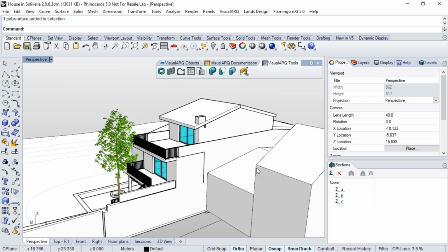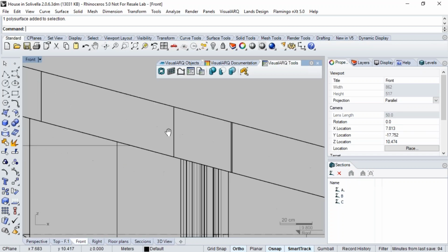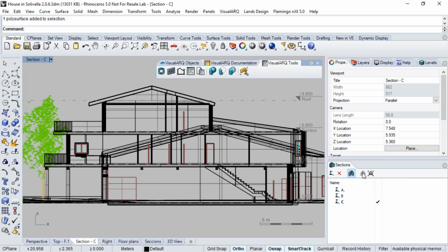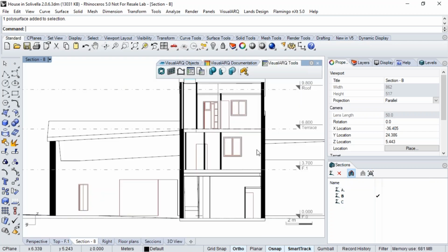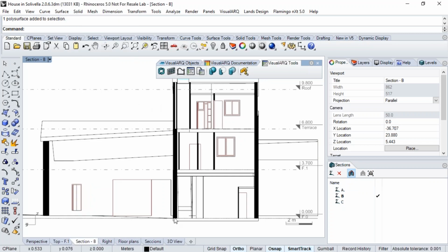Now let's check the section view. When we are in another viewport, again, we can say that in this view we want to see section C. This button just aligns the view to the selected section, but doesn't change the zoom or the display mode, while this other option makes the zoom extents, aligns the view to the position of the section, and also changes the display mode to hidden. This is important again because when we are ready to prepare the page layout...